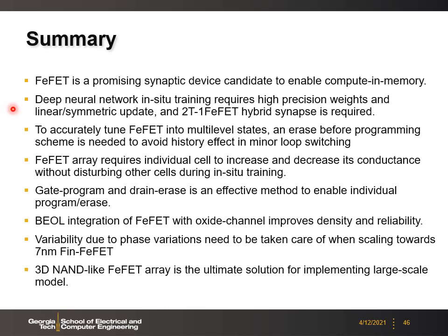Therefore, we think the hybrid synapse consisting of 2 regular transistors and 1 FeFET is promising. To accurately tune the FeFET into multi-level states, an erase before programming scheme is usually necessary to avoid the history effect, as we discovered in the minor loop switching.